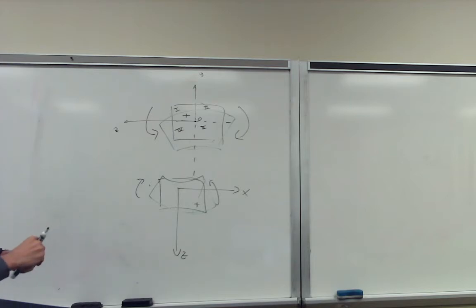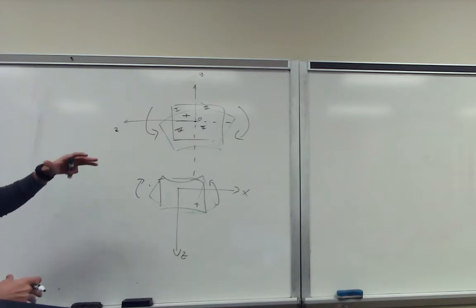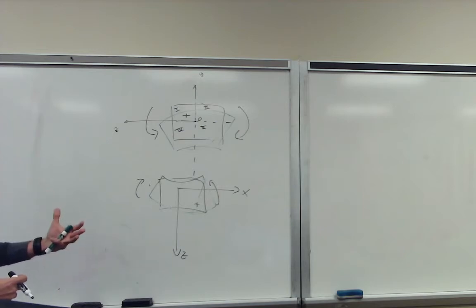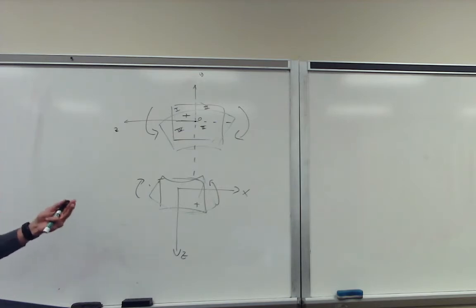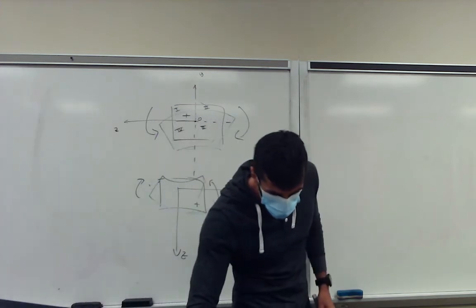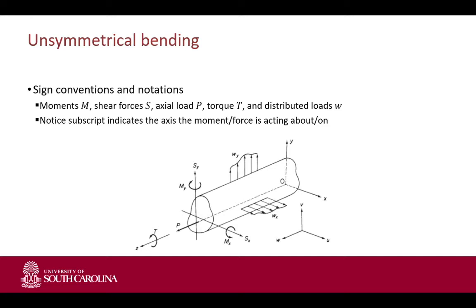So you have to always look at, does my moment, how it's applied to my structure, yield tension in the positive quadrant. That's basically the theoretical way of how I look at it. You can cheat a bit by saying right-hand rule for Mx and Mz, and the opposite for My. That's how I have to remember it.